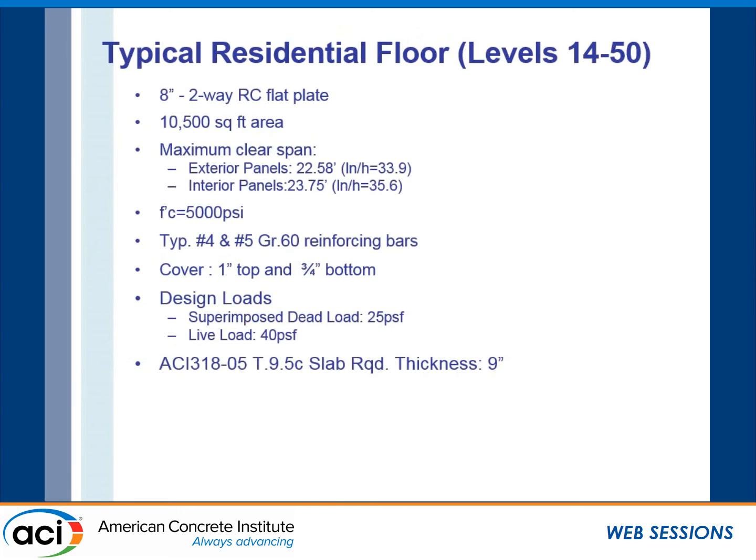The typical floor is just your typical mild reinforced concrete slab. It's an 8-inch two-way flat plate, roughly 10,500 square feet. The maximum spans for the exterior bays are about 22'7", and the interior bays are around 23'9". The L over h, the span-to-depth ratios, are about 33.9 and 35.6.